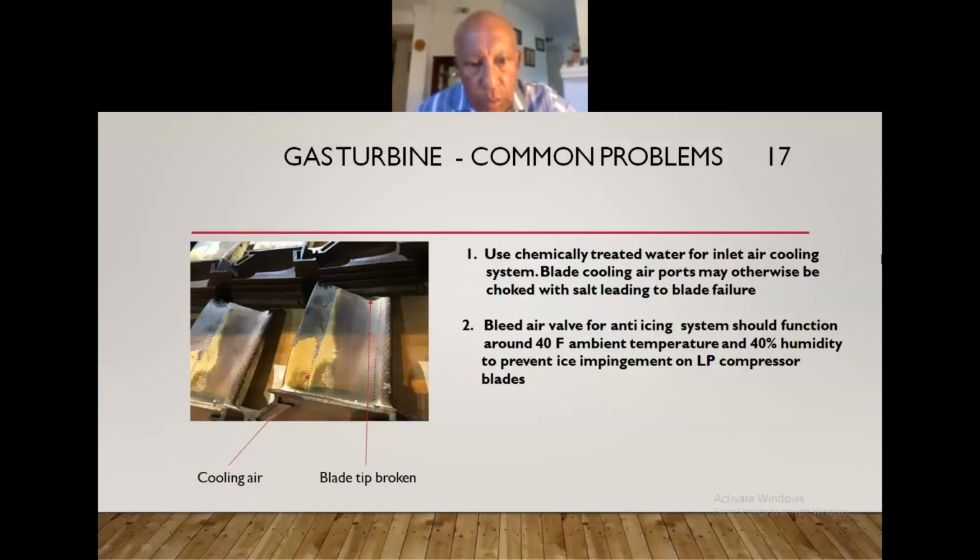So when the 2200 degree Fahrenheit temperature gas hits these blades, they hit that cold air front and do not impart their heat directly to the blades. This particular blade has lost the tip of the blade, and the air comes in here and it has broken into pieces. This is about a $30-40 million loss.